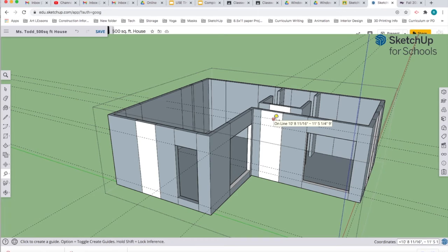Now, for these higher windows at least, and probably for the other ones, I'm going to make the tops all at the 8-foot mark. Now I'm going to click on the edge and drag down, because this is the short window, 1 foot and then space 6 inches. This is where that window is going to go.